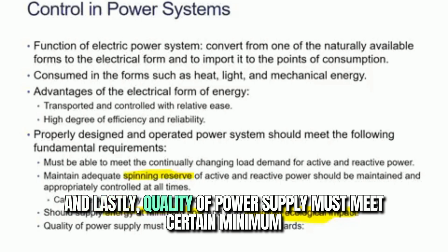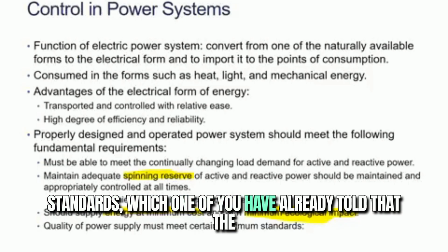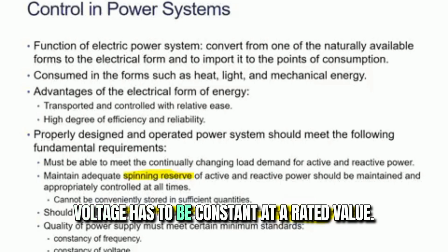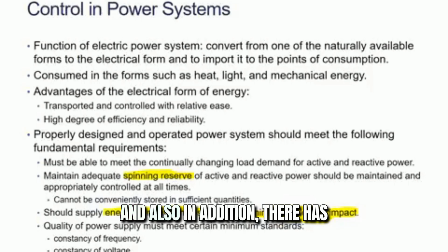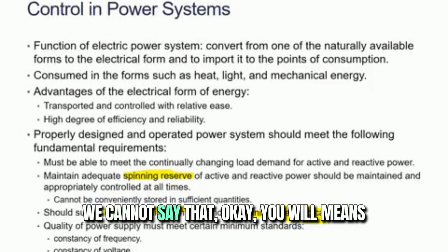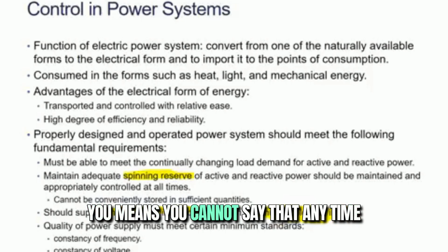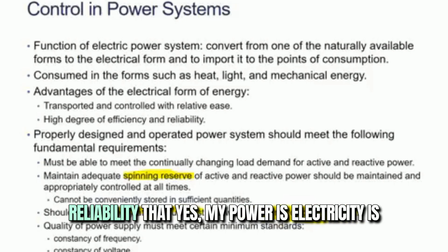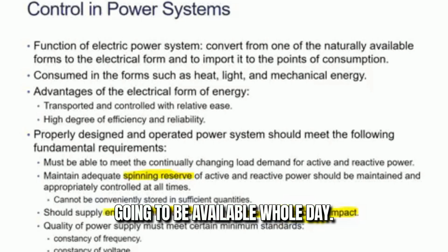And lastly, quality of power supply must meet certain minimum standards, which one of you has already told, that the frequency has to be constant at a rated value, the voltage has to be constant at a rated value, and in addition there has to be some level of reliability. You cannot say that at any time power is not available. So you have to have some sense of reliability, that yes, electricity is going to be available the whole day.